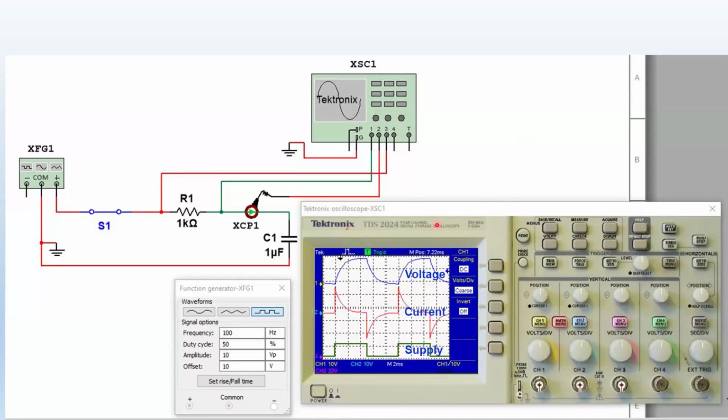All right. So now I built a circuit in Multisim. By the way, this here, if you haven't discovered that yet, is called a current probe. Because an oscilloscope is not able to measure current, it's just able to measure voltages. But there's something called a current probe, and it's one way of displaying the waveform of current. In Multisim, it's solved in that way here. So what do we have here?